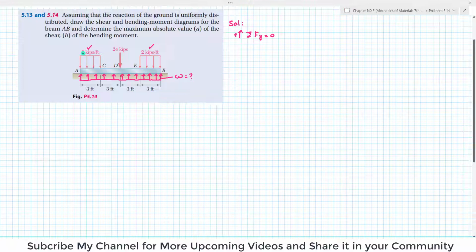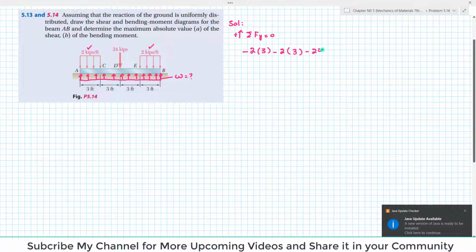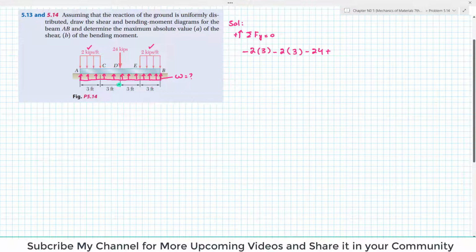So how will we do this? Again, you can see this is a distributed load acting on a length of 3 feet. When you multiply this distributed load, which is 2 kips per feet, with this length 3, it will be converted into a point load. Since this is downward, it will be negative. Similarly for this force, it will be minus 2 into the length over which it is acting, which is 3 feet, so 2 into 3. Another load is 24 kips, which is acting downward, so minus 24. And the fourth load is positive, which is upward, and this is W into the total length of 12 feet, so 12 into W, and their sum must be equal to 0. When you solve this, you will get the distributed load W equal to 3 kips per feet.